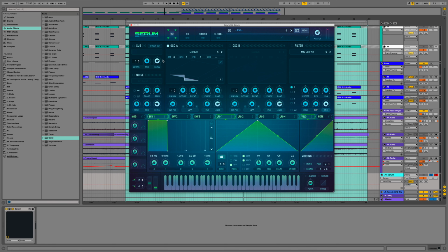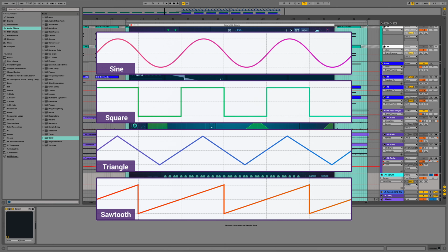We'll start with the oscillator. The traditional analog method of generating sound electronically is with an oscillator, an electrical component that produces an electrical alternating current, or AC. A voltage controlled oscillator, VCO, the type used for music synthesis, accepts a direct current as control information to vary the number of cycles generated per second, or its pitch. The only part you should commit to memory is remembering that an oscillator is a repeating waveform with a fundamental frequency and a peak amplitude.